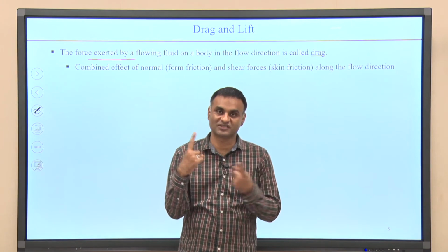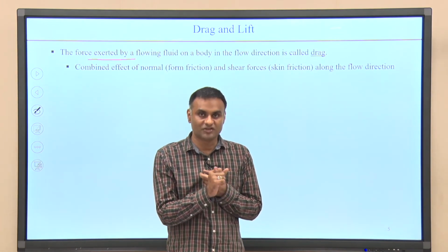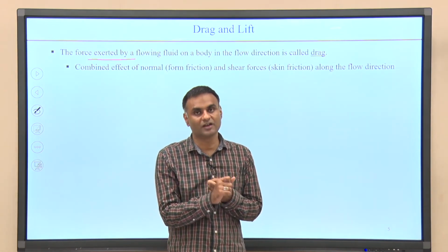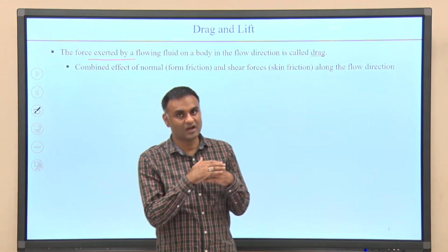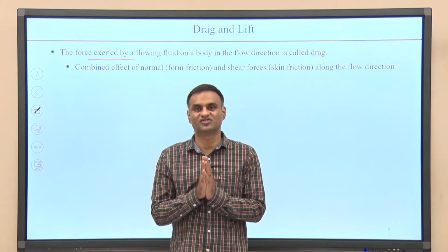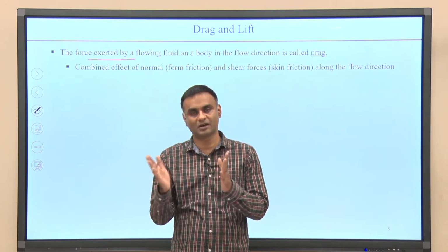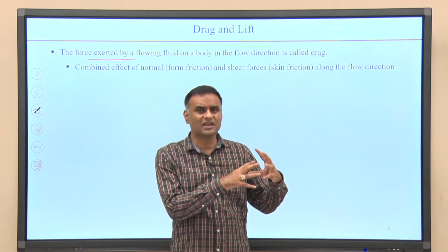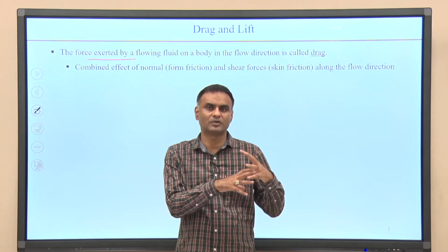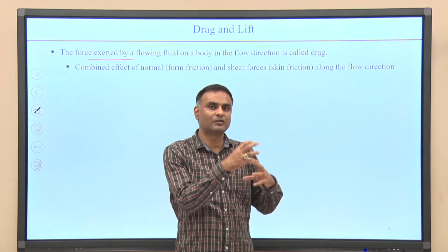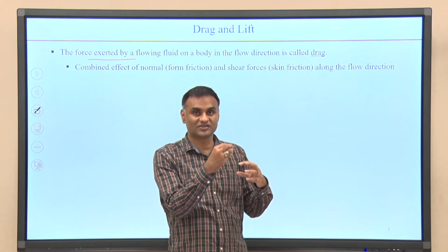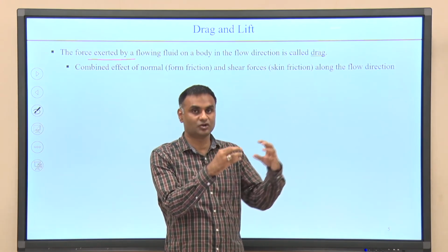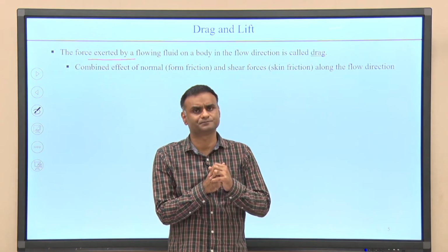So, you can have viscous stress which is normal to the wall, and viscous stress which is tangential to the wall. You can have viscous shear stress which we commonly hear about, and in some cases, for example Stokes flow around a sphere, the normal component of viscous stress is non-negligible, and you might need to consider it.